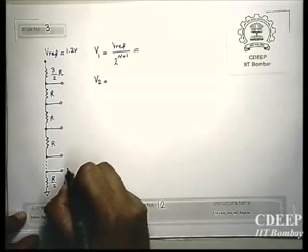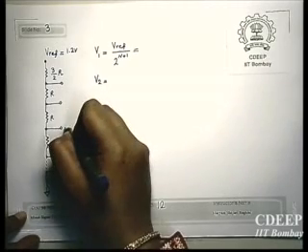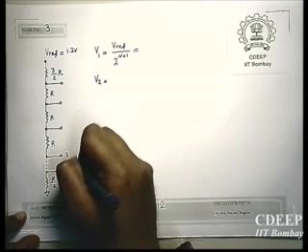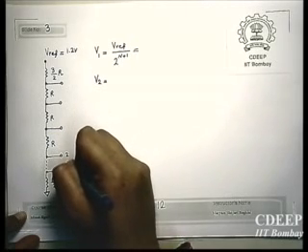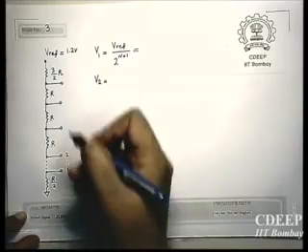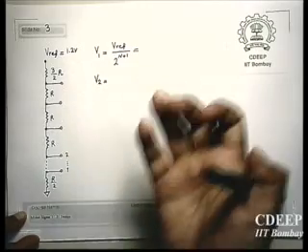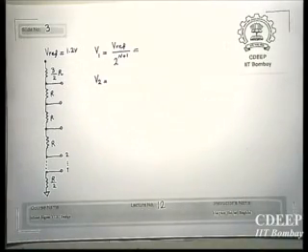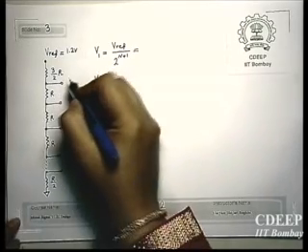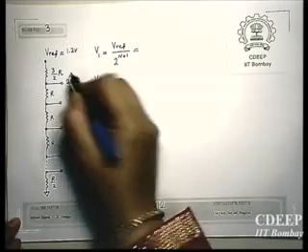Therefore, suppose 1, 2. Actually, this should not be 2, but it's okay. So as we start, like 1, 2, 3, how many reference values do we need? Because it is n bits, eventually we need 2 to the power n reference values. So this will continue and then it will go to 2 to the power n.